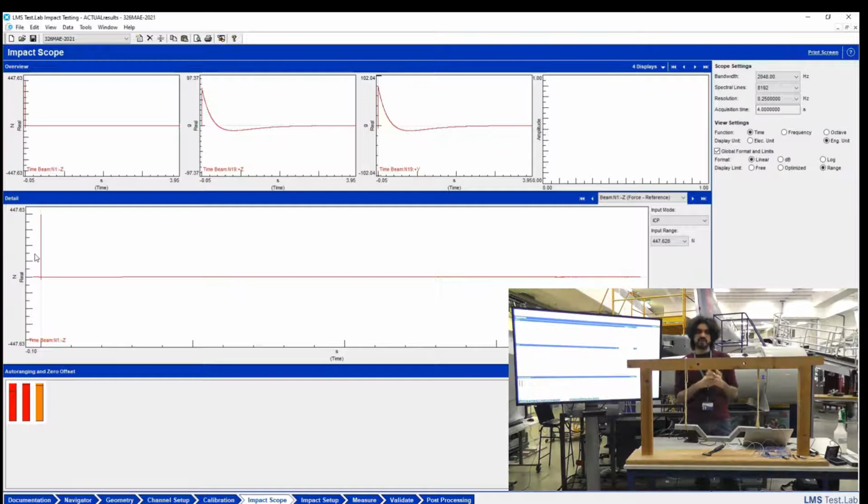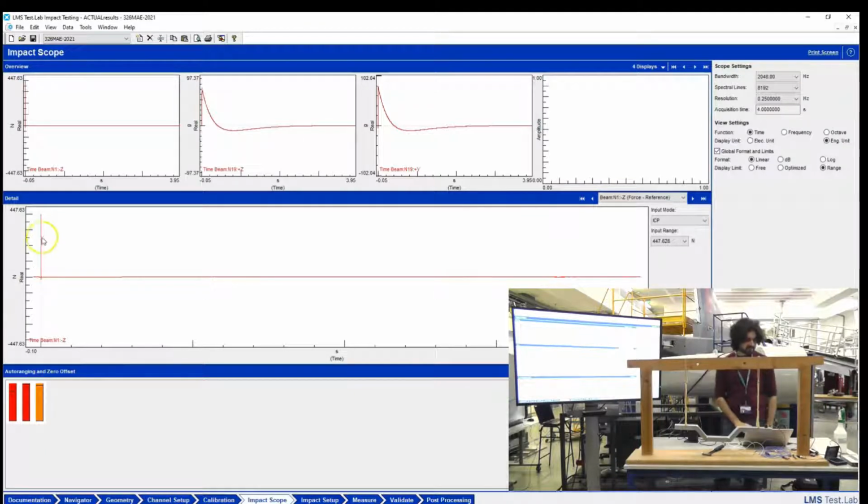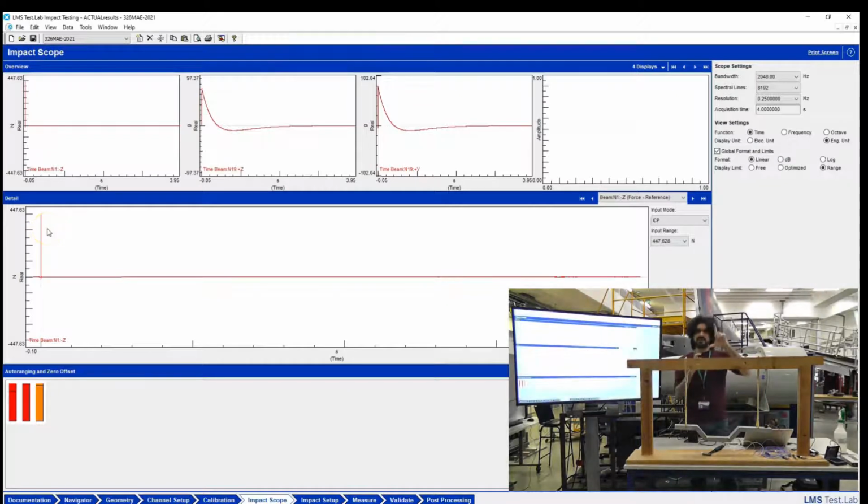So what you want is your signal must not clip, so you must have a level of amplification that gets you to the largest possible value without clipping. And you might be asking, why don't you just have a low level of amplification? Well, if you have a low level of amplification, something else happens, and it's a loss of resolution.